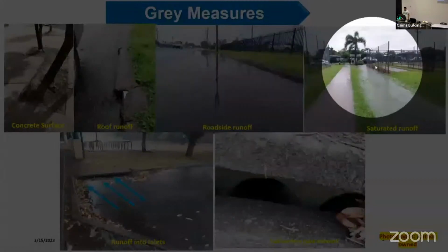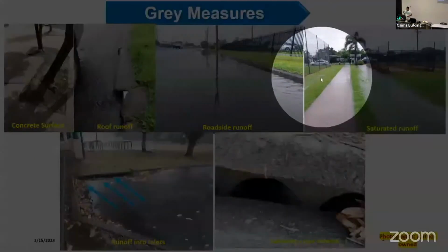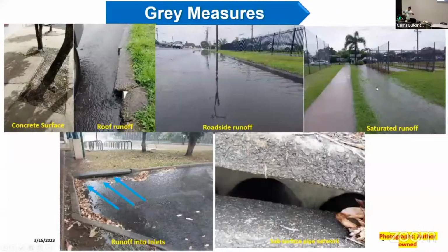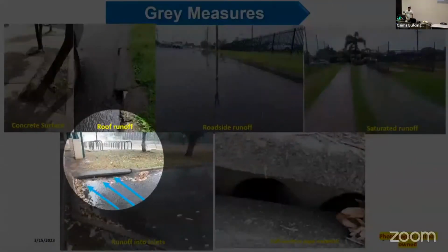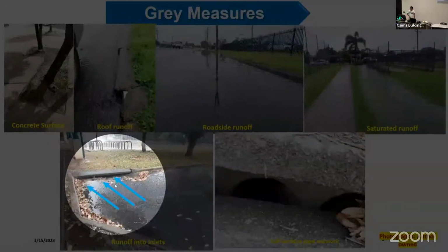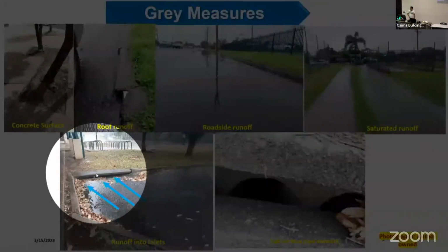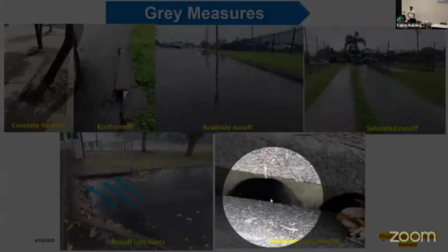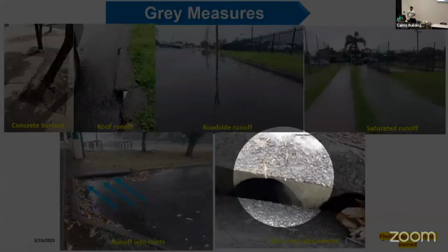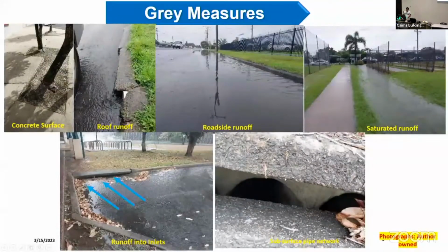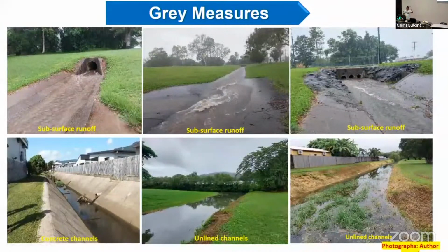And then we have also modified our land structure so much. So when there is rainfall, we can also see the runoff from pervious lands or the open spaces as well. All this runoff is collected at these inlets. There are different types of inlet, but we can say the inlet is the point where everything goes. And then we use these underground pipe networks, which transport the runoff from one place to another, like from upstream to downstream, or south to north, or different places.